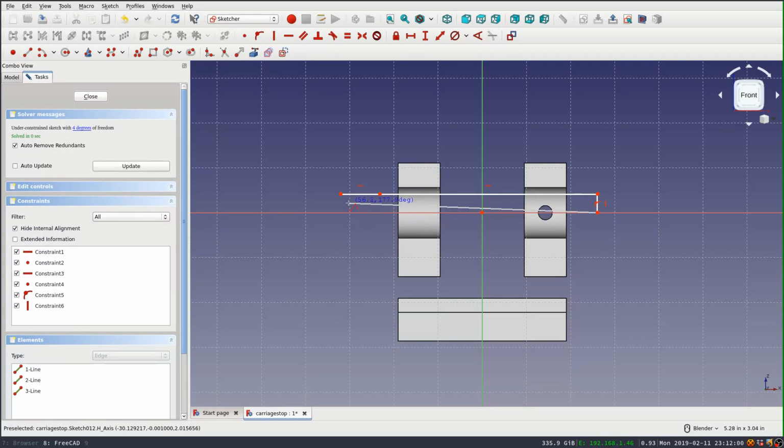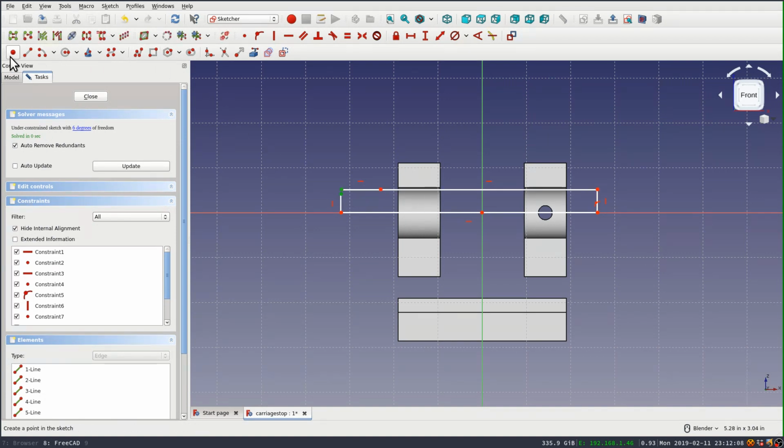And I'm going to do the same thing again. I'm going to draw the top edge in two parts and the bottom edge in one, and this time the bottom edge is going to be directly on the x-axis. Make sure that these 2 points are coincident, and I can set the horizontal length constraint on this. I think it's 2.5 inches.